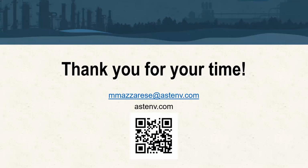If you're in, say, the Japanese beetle zone or the fire ant zone, you have to package your samples a little differently before they come to RPI. Just get with one of us and we can coordinate that with you. Make sure we've got a good plan for the field, how many samples we want to take, for both groundwater and soil. RPI doesn't cover shipping or coolers or glassware, because the service is free. As long as you get the samples to us, we'll run them for you.